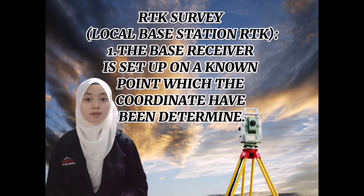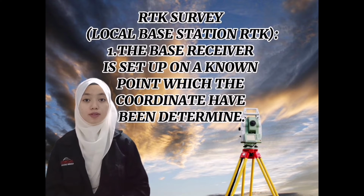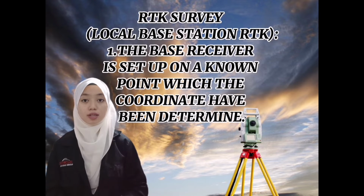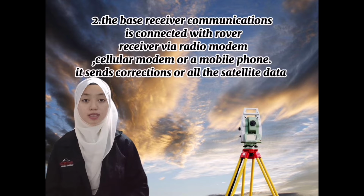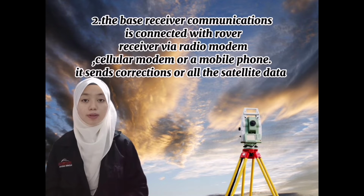RTK survey, local base station RTK. First, the base receiver is set up on a known point whose coordinates have been determined. Second, the base receiver is connected with the rover receiver via radio modem, cellular modem or a mobile phone.